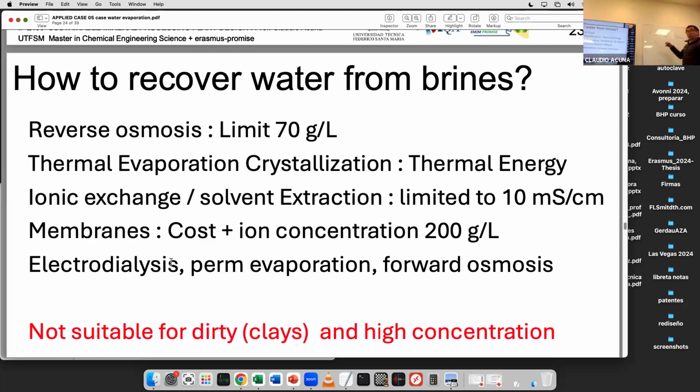Energy consumption to produce from seawater with 50% recovery. 50%. This is the actual technology. We cannot do more. So it means starting with 35 grams per liter of salt, residual water 70 grams per liter, and the consumption is 3.2 kilowatt hour per cubic meter. This is our current technology. Very top. Okay? So the water problem has been solved. We only need energy.